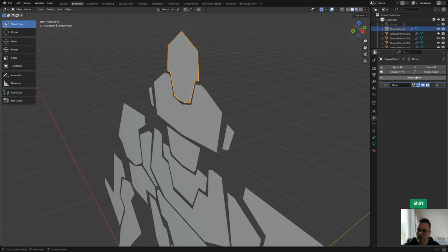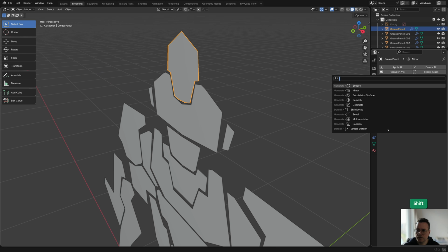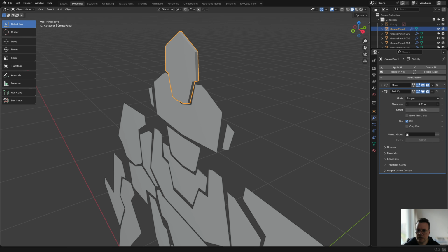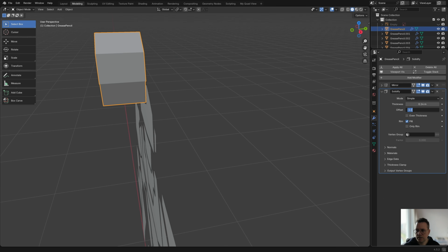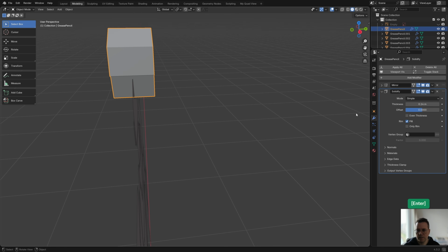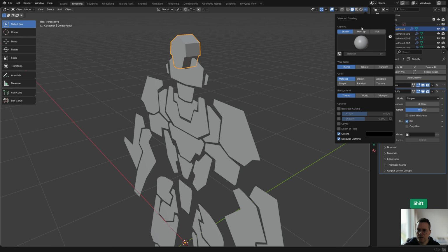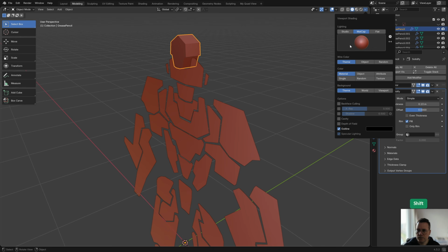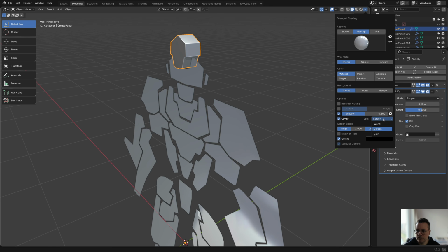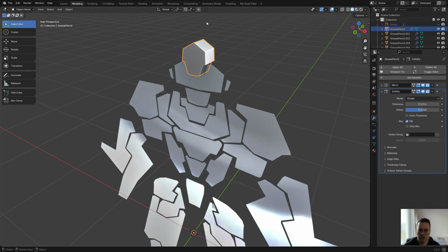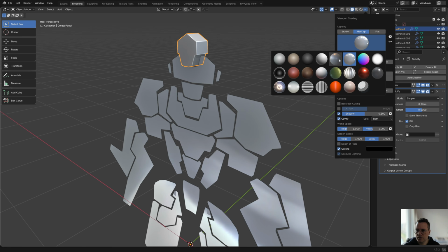And so now we can start adding some thickness to this. So go to search and solidify, and then just increase the thickness. And instead of it going forward like this, we can set the offset to 0. Then it just makes the thickness from the center of the object. Let me just quickly turn a matcap on so that it looks more interesting. And I'll also turn on cavity and shadow and set this to both. That just looks better. Maybe let's use a different matcap.